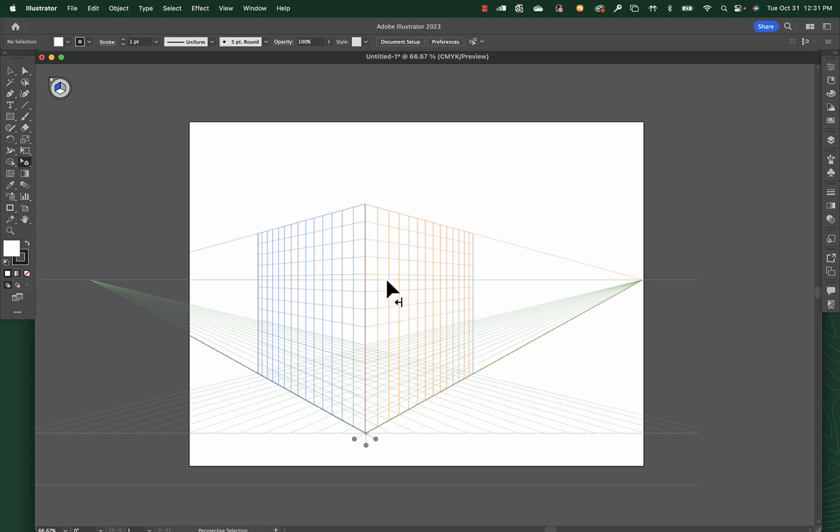But as I hit different shapes, if I hit M on my keyboard and I draw in a shape, even though I'm on this side of the grid, it still thinks I'm on the left grid, and so it's continuing this grid over onto this side. So always make sure that you have the proper grid side selected for where you want it to go. And as you position that, it pops it into place. It's just filled with the default fill and stroke at this point.